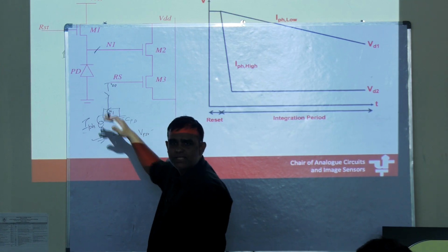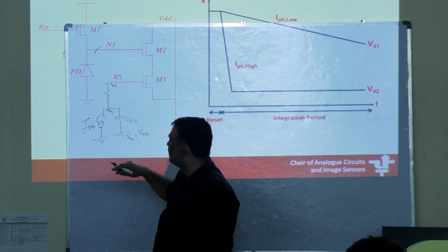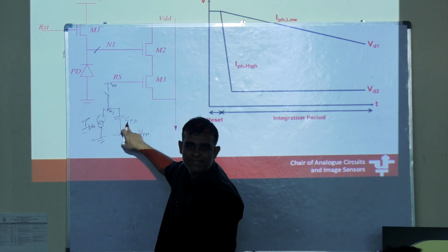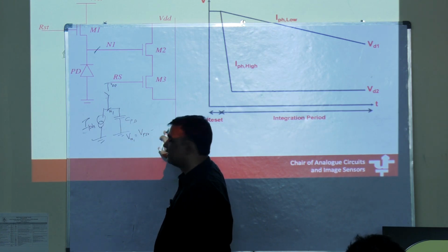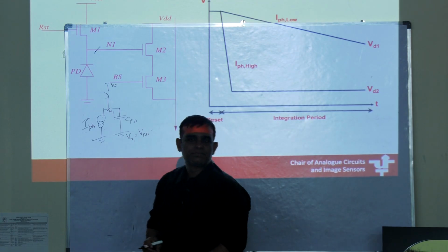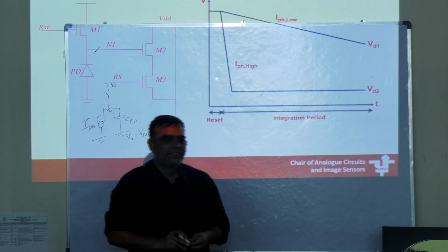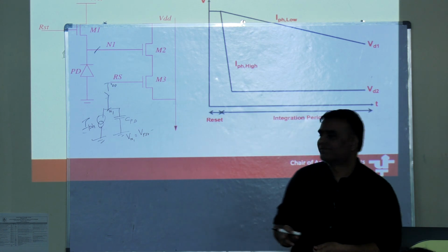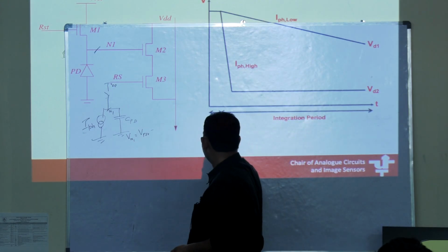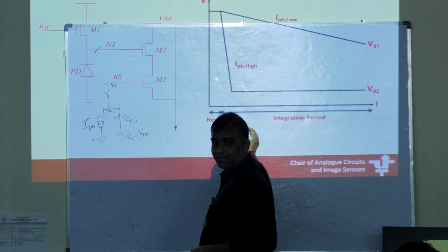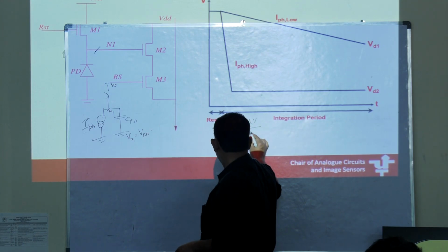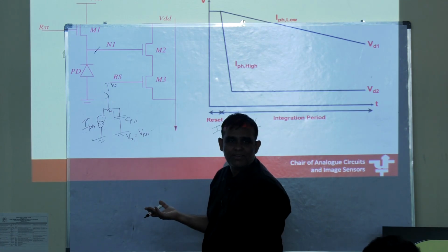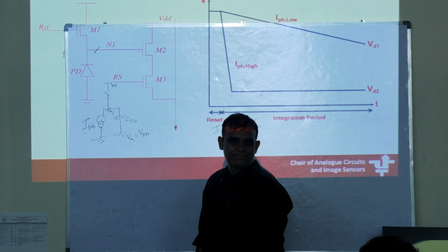So now I know my voltage is falling down, that I know qualitatively. The voltage is falling down because this I photo is being integrated on this capacitor. So what will be that here? Will it fall down? High school maths, what's the current in a capacitor? So it's dependent on time. Right? There is no resistance in the circuit.